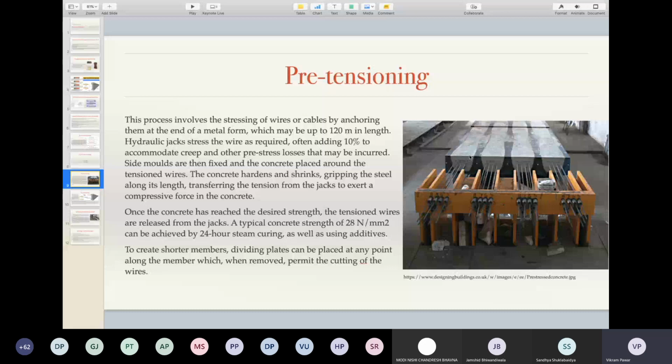So when you are expending on a high amount of steel, high strength concrete, high strength steel, as well as these customized molds, then what is the advantage? Because everything seems to be expensive. So what is the advantage? Whether there is an economical advantage. So when you do that, the economical advantage in effect is drawn from how carefully this is modulated. For example, for the same length of the beam, if it was a regular beam, it would have been at least 1.5 times this deep.